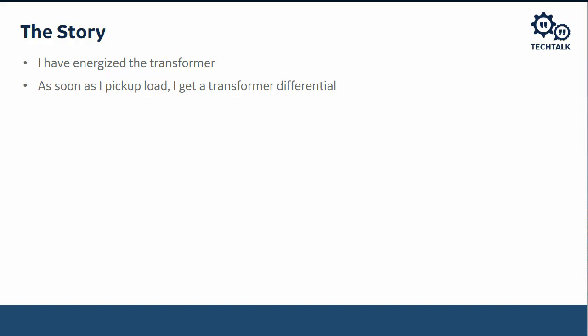They have verified the wiring from the CT all the way to the relay. And both transformers and both transformer relays are wired identical. They are drawn identical. On the drawing itself, they are wired identical from the CT all the way to the transformer. So one of these transformer relays has the problem. The other transformer relay doesn't have the problem. So what is unique about that transformer that has the problem?